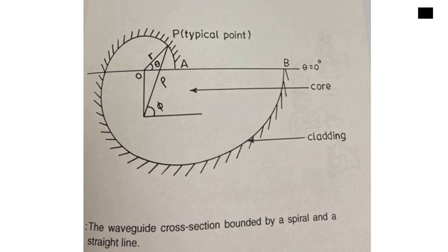Omega is the angular frequency, epsilon the permittivity, mu the permeability, and beta the z component of the propagation vector. While using the separation of variables technique, we determine the equation for the core region. This is the well-known Bessel differential equation, and nu represents the order of the Bessel function. The solutions of this equation are simply the Bessel functions.